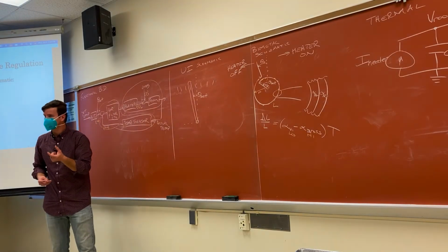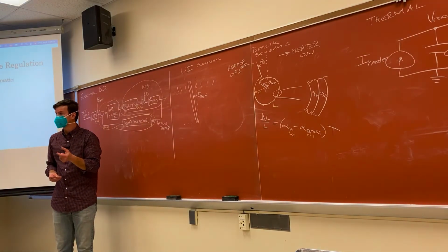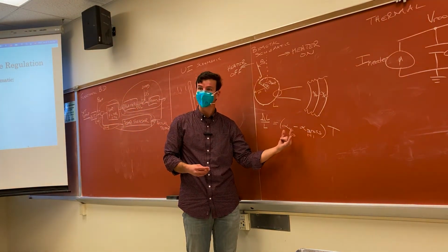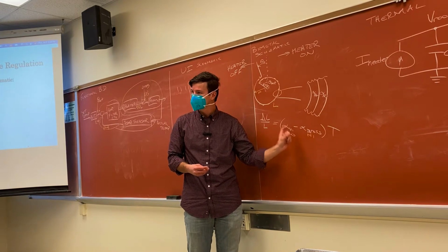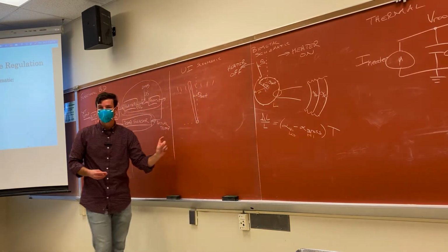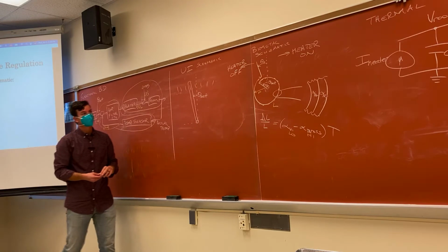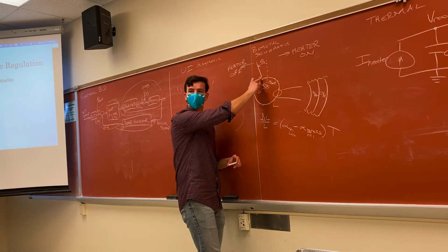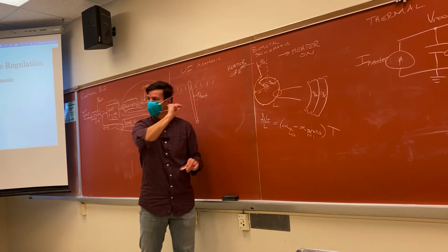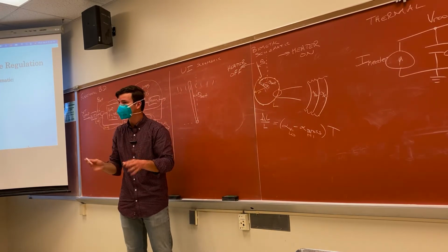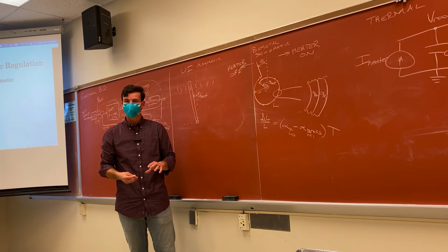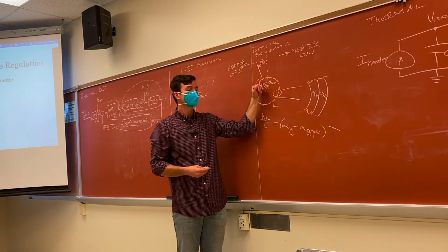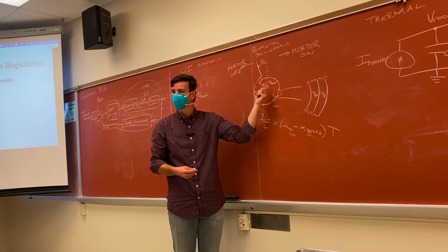And the addition is subtle here. Well, the subtraction is even more subtle, because the first time I did this, I had these in the opposite direction, and it was an addition, but we want it to be a subtraction. The addition happens because this angle is this angle plus the angle given by the coil. That's a very subtle point here. There's no summing amplifier, there's no business like that. The addition is simply one angle adding to an arc starting at a different angle.